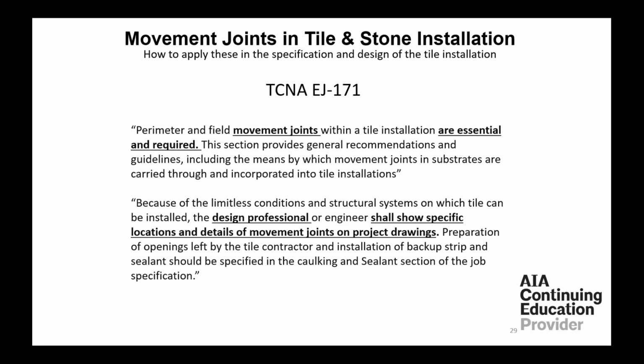It's really difficult for a tile installer to understand the movement within a building. That's not their expertise. That's not what they went to school for. So it should be cooperative work. What I recommend to design professionals, especially on large commercial jobs, is request a shop drawing of where the movement joints should be. What I mean by that is they need to provide some guidance, but then in the end, come to an agreement through shop drawings on where they're going to be.